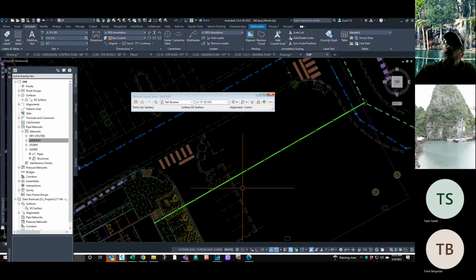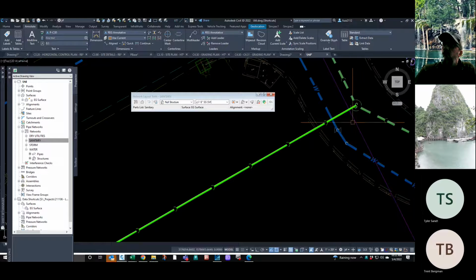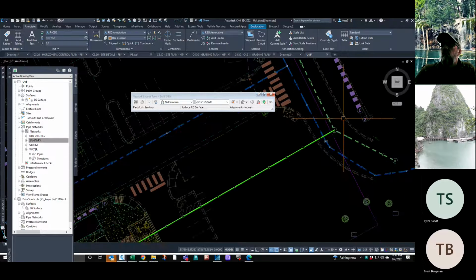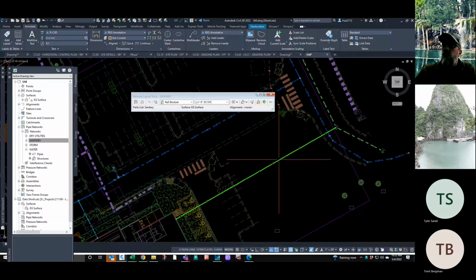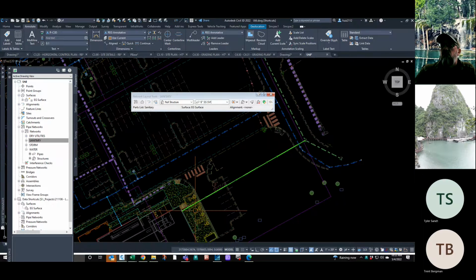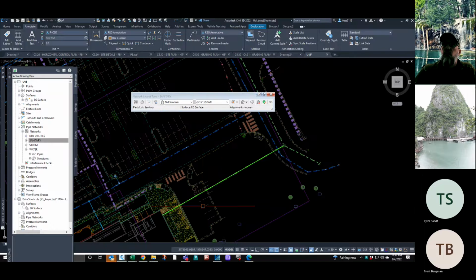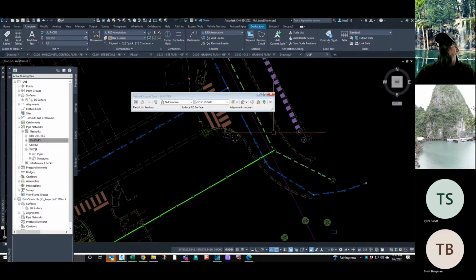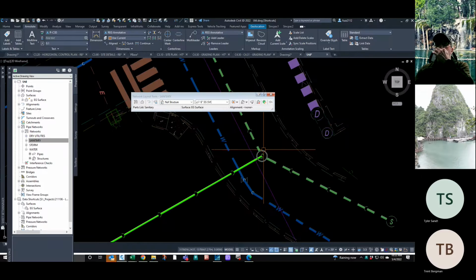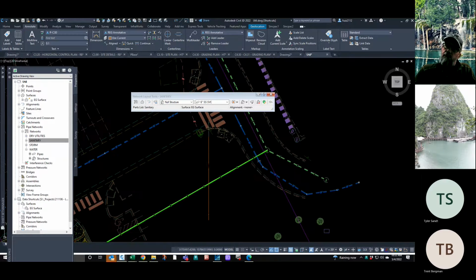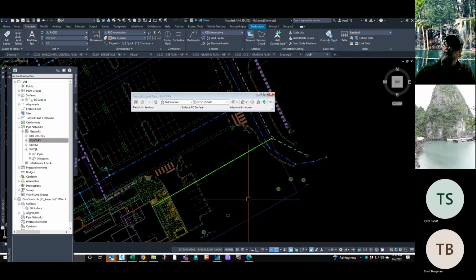So same thing in our overall utility plan, we would just label this as pipe and material, and then we would label this as an existing 4-foot manhole. If we were to do a plan and profile of this, we would run this profile, show this existing manhole and the pipe, and show all the information in the label for this structure. For services, no plan and profiles.